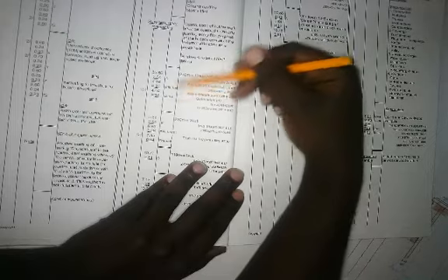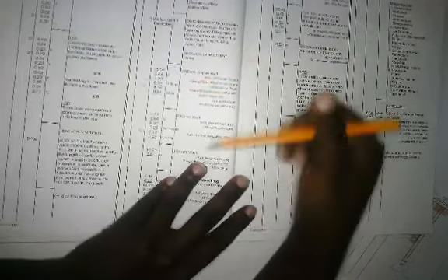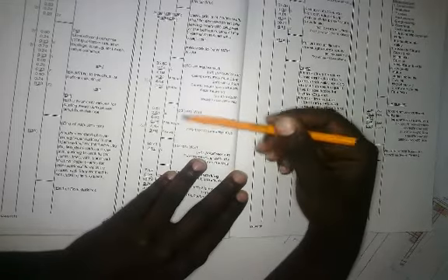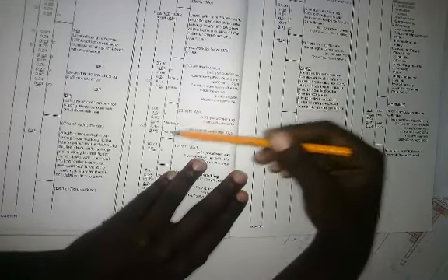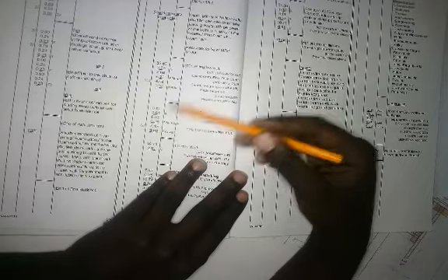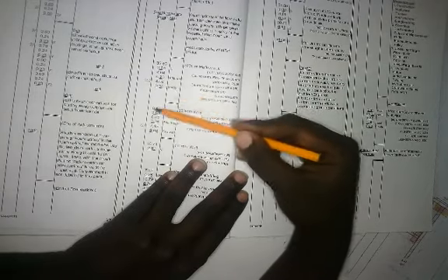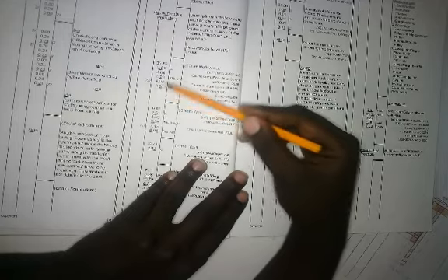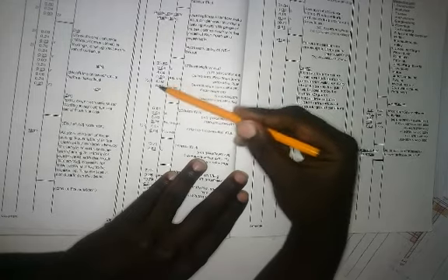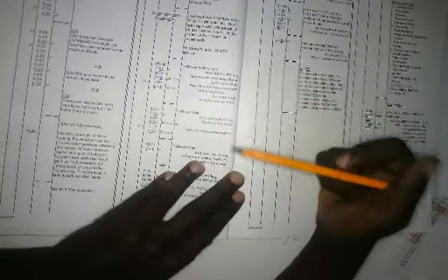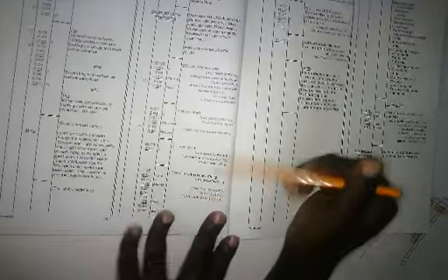That's your height. And then your beam filling is going to be 3 courses, 3 courses of your beam filling. That's 3 times 85, that's 255. And then you're going to do it in selected places. You're going to do your beam filling, and this is for cables. And then you're going to come to the 230 wall, which I'm assuming is going to be a firewall.